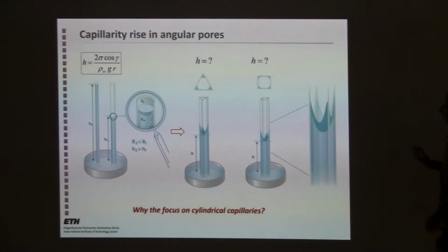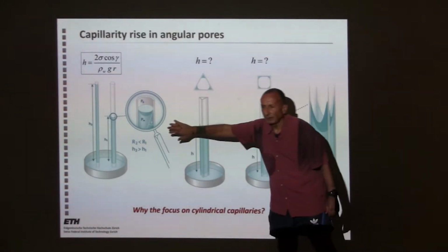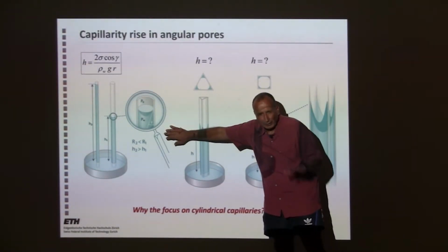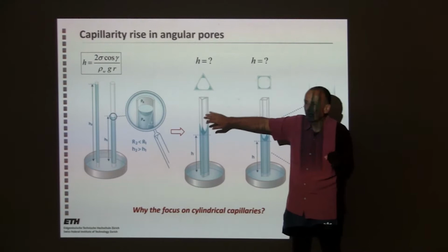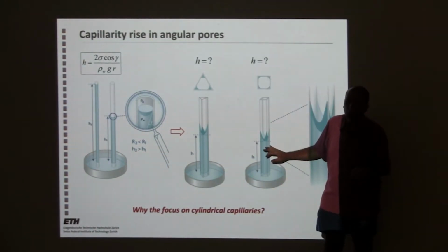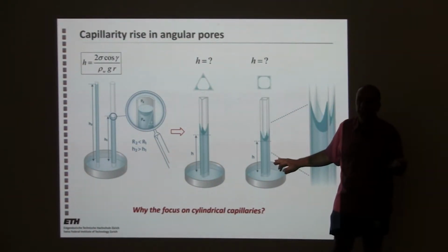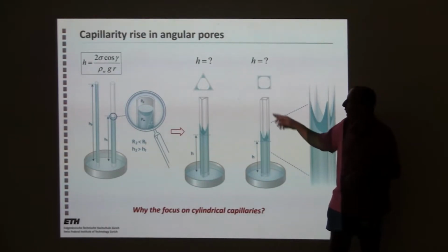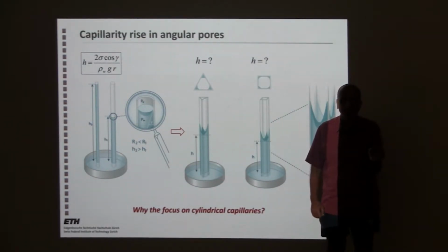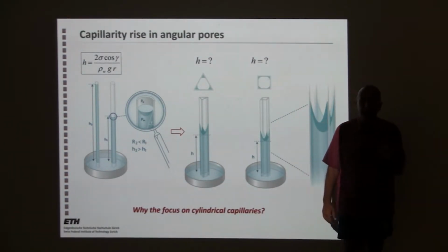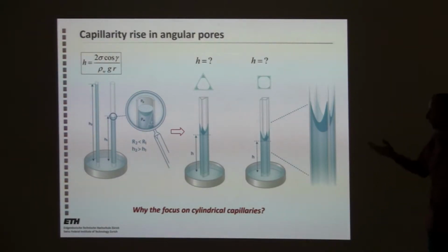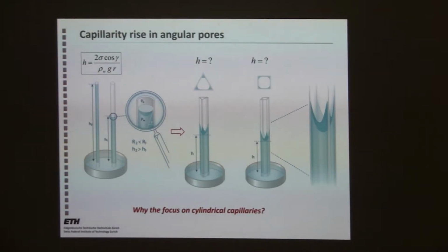Most of the textbooks talk about capillary rise for cylindrical capillaries, which are, as I said, a very special type of capillaries. But there is no reason for you not to develop understanding for capillary rise and water retention in angular capillaries. The physics and the geometry are simple enough for you to be able to make this transition.